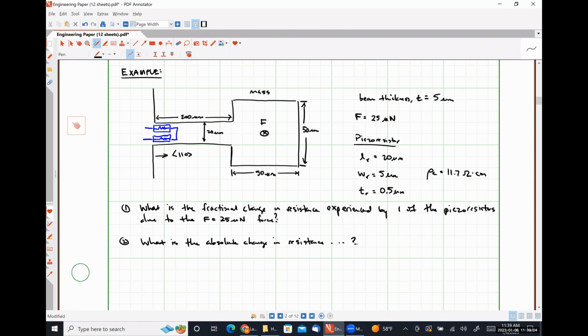So we've talked about the importance of the thickness of our piezoresistor. What about the length, right? Anybody have any thoughts regarding the length? Why that might be important? Is the stress/strain that the cantilever beam undergoes constant? No, its maximum value is at the anchor point, and at the free end of the cantilever beam, it's effectively 0. So we want to make our piezoresistors short in comparison with the length of the cantilever beam itself, so